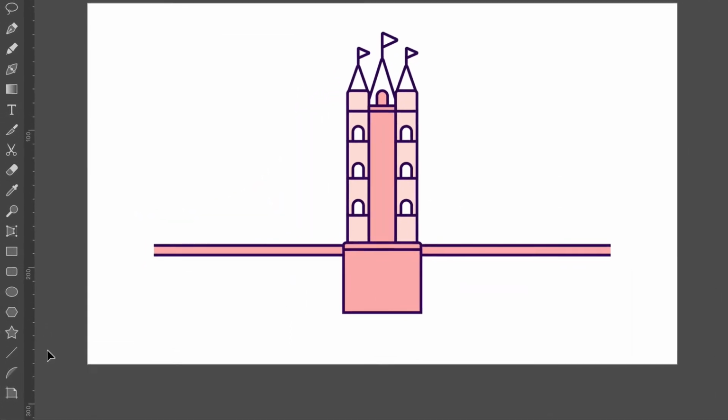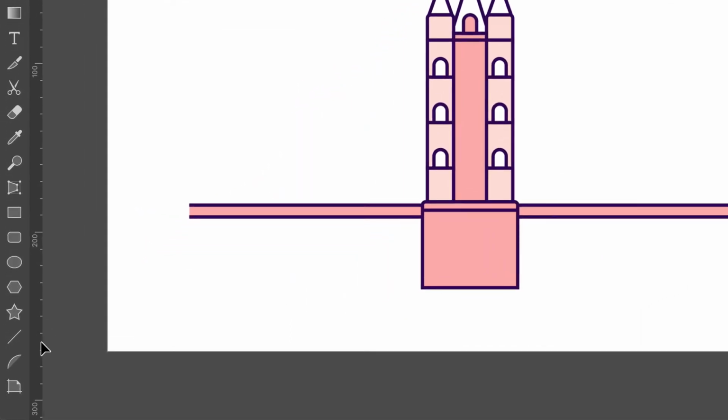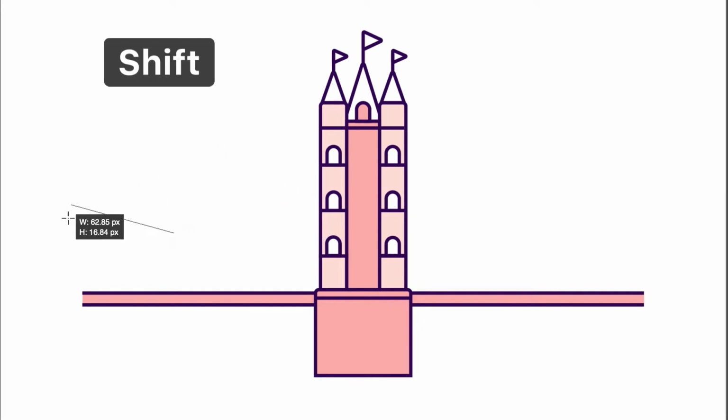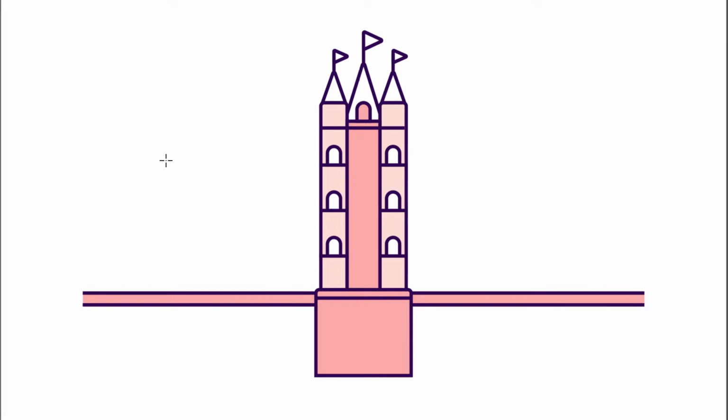To begin drawing our first straight lines, we need to select the Line tool on the Tools panel or press / on the keyboard. Then click on the canvas and drag in the direction we want the line to go. Release the mouse button at the point where the line should end. If you press and hold the Shift button while drawing the line, it will snap to every 15-degree increment. This is especially useful if you want to draw horizontal or vertical lines.